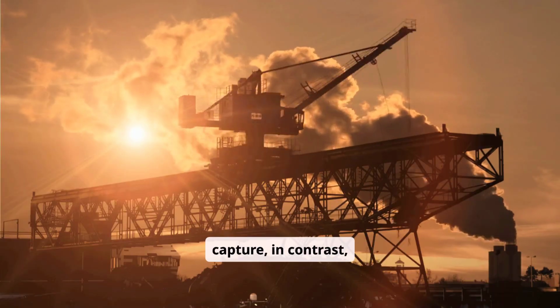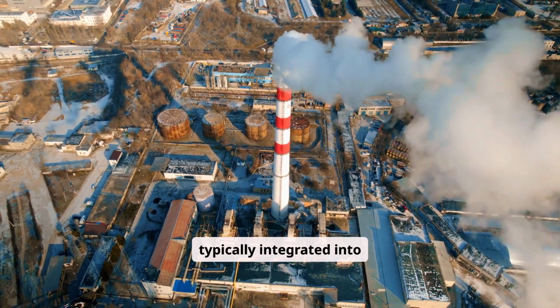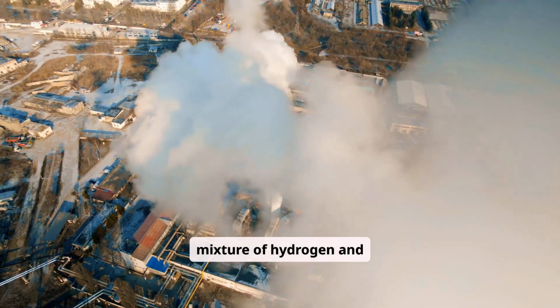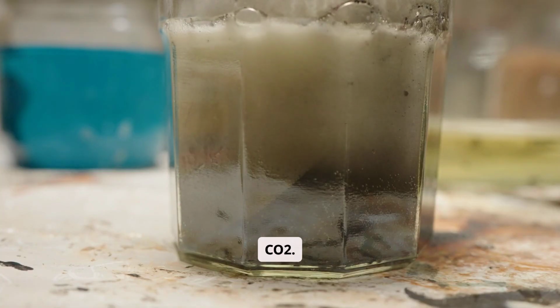Pre-combustion capture, in contrast, separates CO2 from the fuel before combustion occurs. This method is typically integrated into processes like coal gasification or natural gas reforming, where a syngas, a mixture of hydrogen and carbon monoxide, is produced. The carbon monoxide is then reacted with steam to produce more hydrogen and CO2.